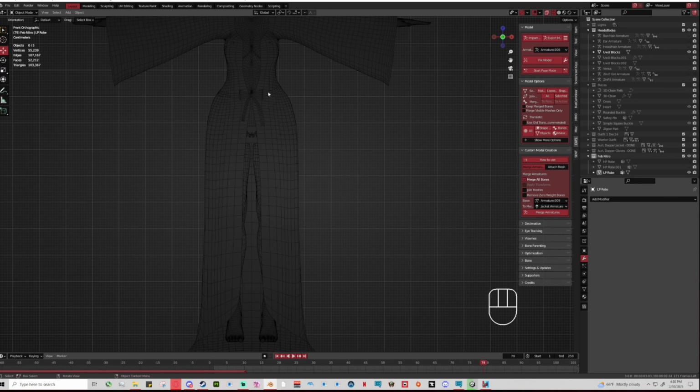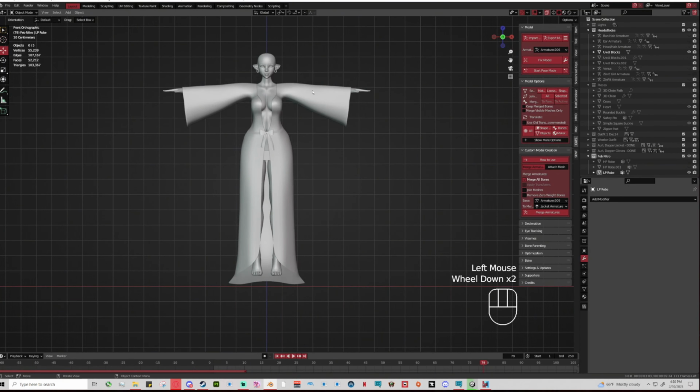So like I said, if you ever are in there texturing and you're like, oh, I can't get this to look how I want it to, just jump back into Blender and redo where you put your seams, and that will help a lot. I don't know how many times I've had to redo my seams to get a texture to work. So it is a little bit of a learning curve, and it's really just thinking about where things need to be separated and then making sure that you do everything we did, especially clearing your transforms, and that will help your textures to not stretch so funny.